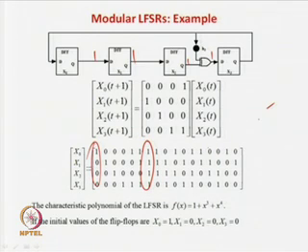It is very important to find out how you select the seed vectors. For example, if these are the 4 vectors which are actually used for my testability case, then better I start from this one, and very quickly from here up to here I will get all the required vectors for testing, and then my job will be done. Then I can reset back here. Obviously I will give this as the seed vector.